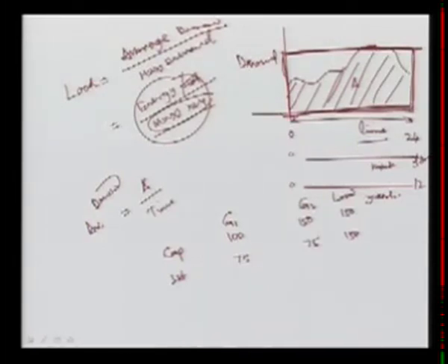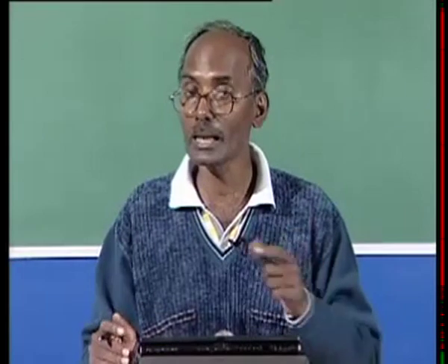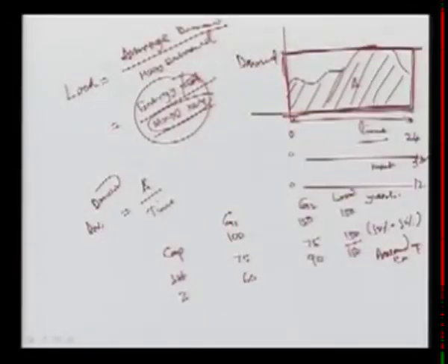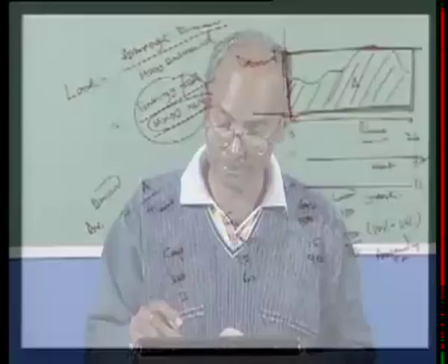Again the total of G1 and G2 is equal to the load. This is based on 50%, loading 50% without any problem. Another criterion, second, is that we can load according to the capacity. This is 100, this is 150, so we have to load here 60 and here 90, and again we just meet our load demand. So it is loaded according to capacity: capacity is less, load is less; capacity is more, you can load more.